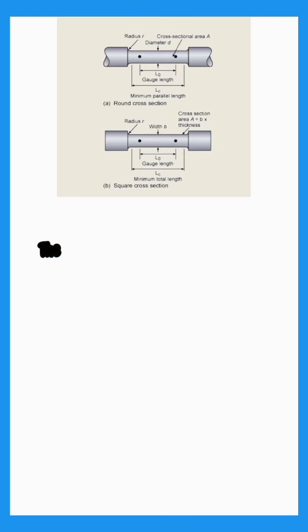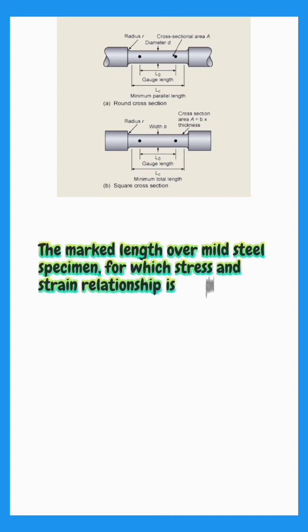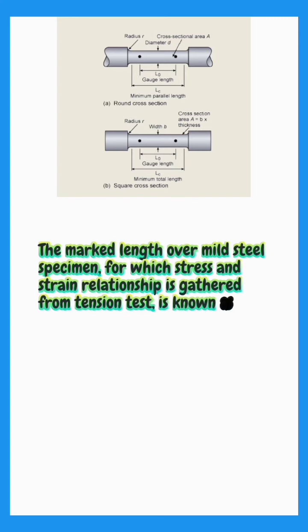Stress-strain curve of mild steel. To know behavior of different grades of steels under loading, we need to perform tension tests over them. When a mild steel specimen bar is used in universal testing machine, its length between jaws is marked at 2 points, over which the extensions are read at different rates of loadings.